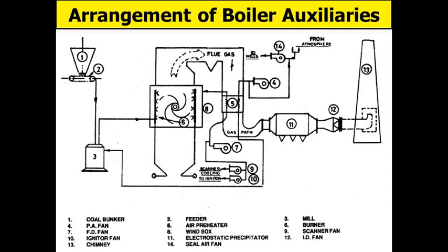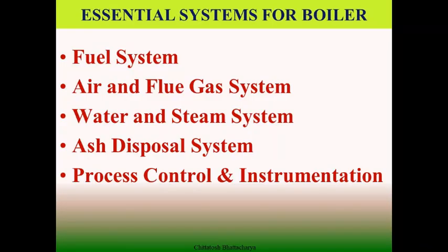Even the residual heat, when the water steam circuit is not absorbing the heat, is absorbed for preheating of air, and post preheating of air, the exhaust flue gas is passed through the dust and suspended particulate matter separation system so that all the fly ash is arrested and clean flue gas is evacuated with the help of the ID fan through the chimney.